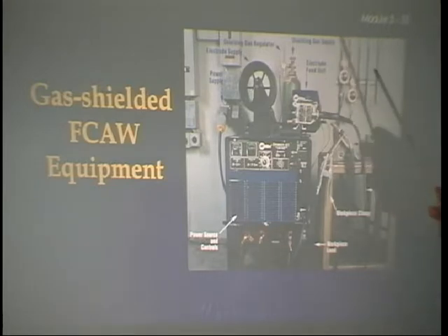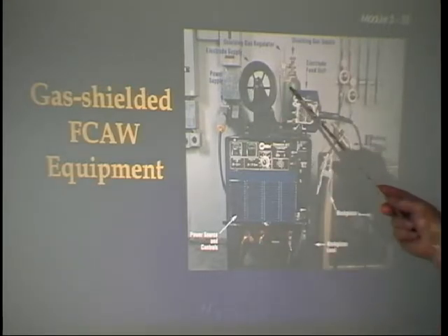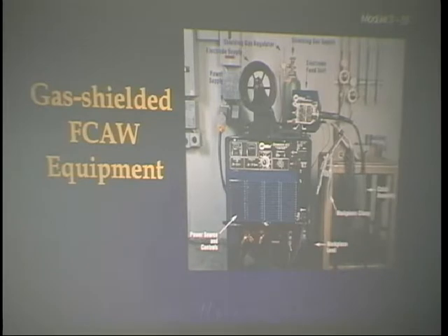We have our gas, so we know that if it's Flux-Core and we have a gas, we know that it's gas shielded or dual shield. Remember that name, dual shield.